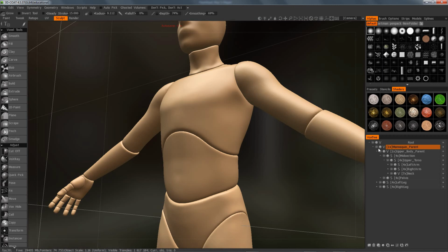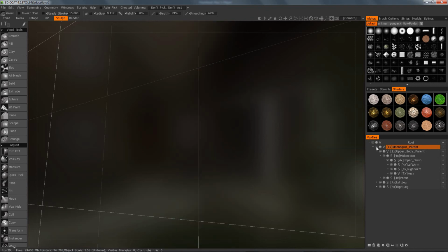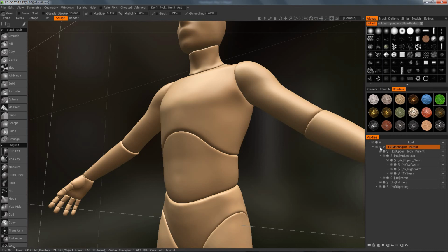It's a tree. If I close the top one, if I turn off the top one, they all disappear. By the way, you have three options here. You have visible and invisible. This is ghosted, which is not going to change anything at the folder level. And then your voxel versus surface mode. This folder and everything under it is resting inside of the folder on top. You can see that they step in like bullet points.